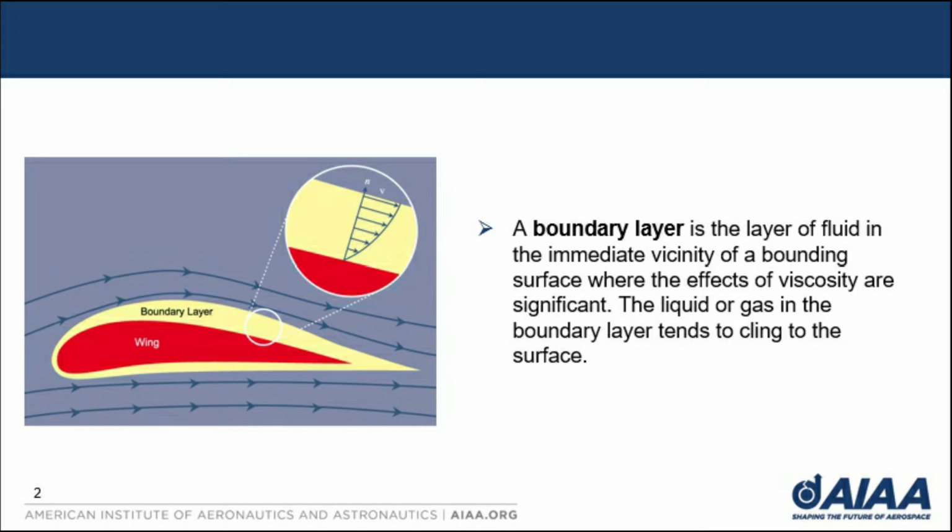There are two types of boundary layer which depend on the Reynolds number. The Reynolds number can be defined as the ratio of the inertial forces to viscous forces. It is used to categorize the fluid systems in which the effect of viscosity is important in controlling velocities. So if the velocity of the fluid reaches a certain Reynolds number, it will determine the behavior of the fluid, naming it laminar or turbulent flow. Thus, we have two different types of boundary layers, which will be laminar and turbulent boundary layers.